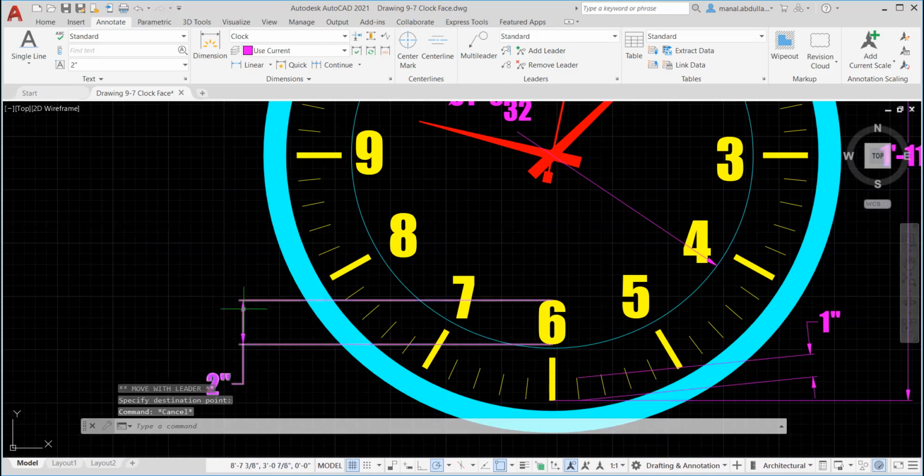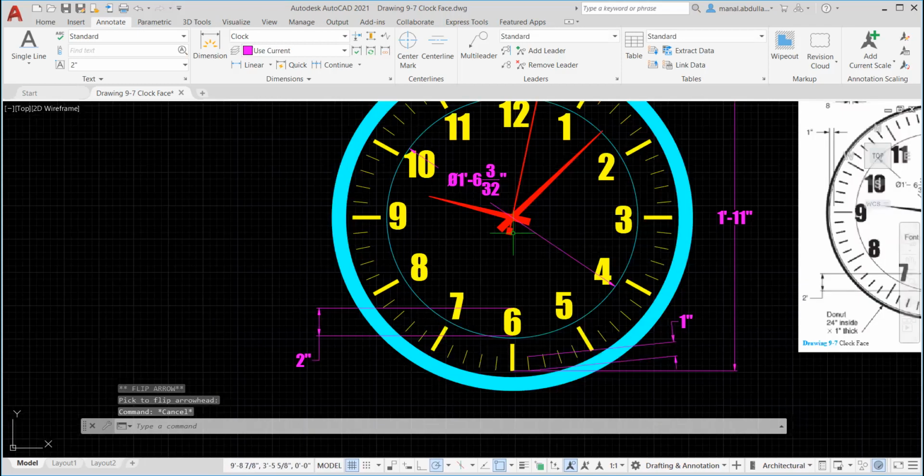Also remember that clicking on the arrow grips, you can flip the arrow. So if you need the arrow from outside, you can flip it. Okay, here you can flip each arrow. You can get it back by clicking there, flip it, and put it back inside. So remember to do that, and we change the dimensions here by moving the text.